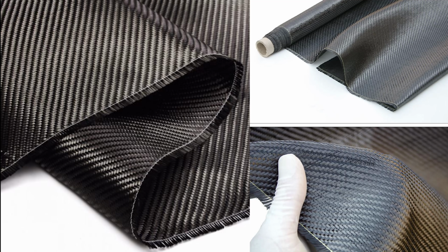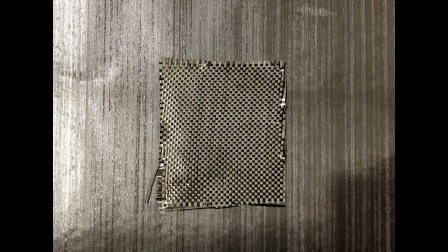Most of a laminate is not weave, basically. There are exceptions to this, but nearly all laminates you see and have used are made out of UD, unidirectional layers, meaning that they're not woven. And then it's just the outer layer that is woven, basically.